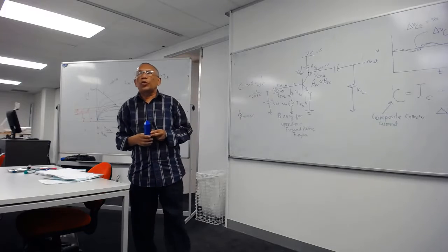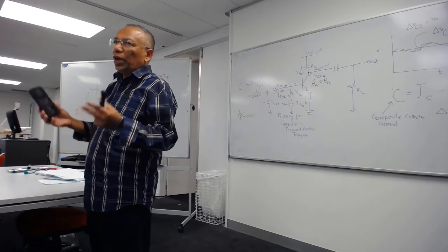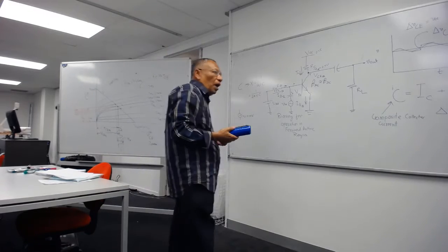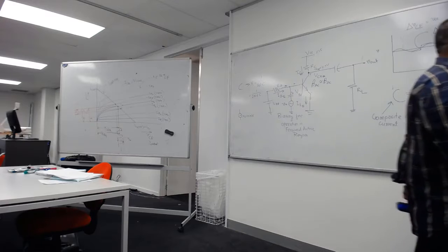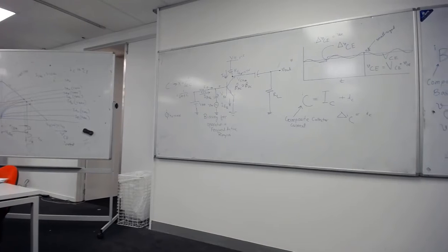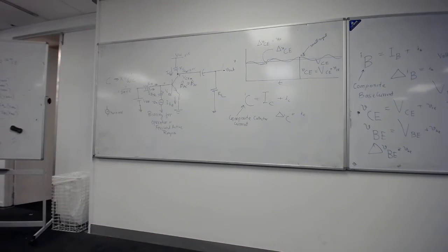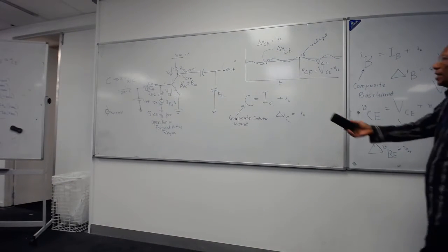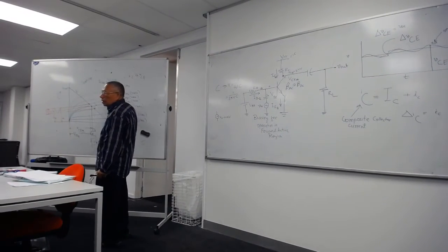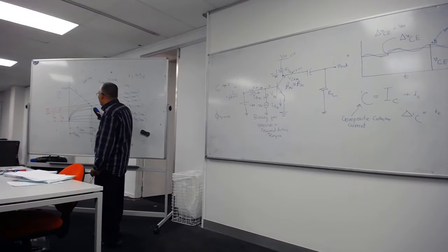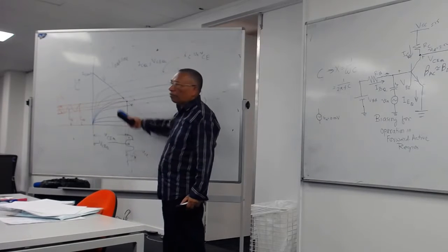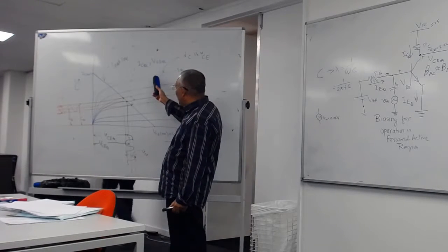Okay, so now what we will do is explore the modeling of the BJT, first starting with the DC model and then going into the AC model for doing your small signal analysis. As you have seen from that graph over there, you can do small signal analysis, AC analysis, graphically also. If you know all these characteristics in detail, you can use a graphical system to determine the AC analysis. So you can get everything from this graph if you know these characteristic curves exactly.